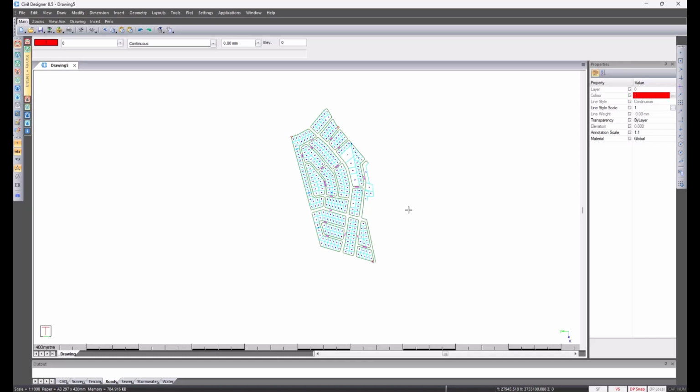Now we need to do the same for the surveyed information. You could straight away go to your survey mode, select transformations and group. But I want to show you some more design features. So first of all, I'm going to rescale the survey. I'm going to give it a different coordinate set, and then we'll come to this transformations functionality. Some of our clients find it beneficial to go and put in a big geometry cross over here so that you've got something to geo-reference to.